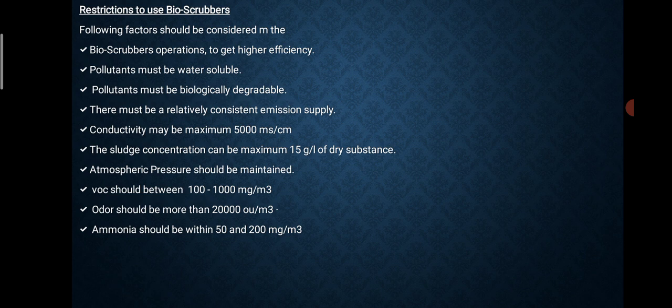Conductivity may be maximum up to 5000 mS per cm. The sludge concentration can be maximum 15 gram per liter of dry substances.